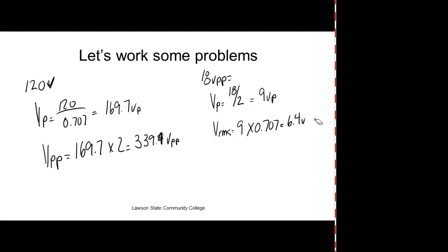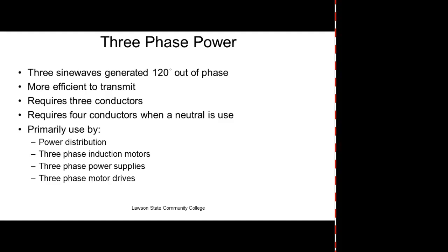Now here at this school, a true RMS meter would not do you any good at all, except showing somebody, hey, I got a true RMS meter. And in most applications, it's not required. But if you get out there and you're working on variable speed AC drives and stuff like that, those suckers generate non-sinusoidal signals, or signals that are sine wave. Three phase.